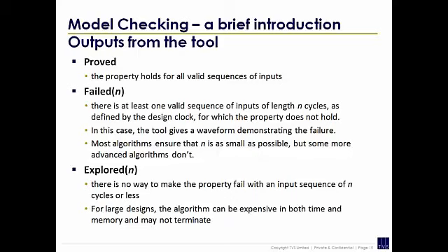And the other thing it does, and this is the big drawback on formal, so again one of the things you can always remember from tonight, a big drawback of formal is that this state space is exploding, as I say, down every single cycle, the state space is getting bigger, bigger, bigger. The formal tools can run out of memory and fail to do the proof. And it can say, I got to cycle 10 and I didn't find a failure, but I couldn't prove it either. I haven't proved it yet. It will just say, I've explored it for 10 cycles, but I haven't proved it.